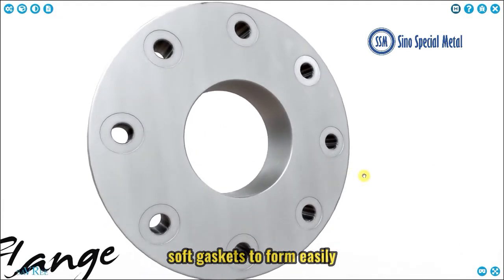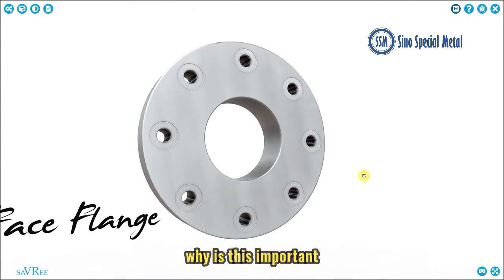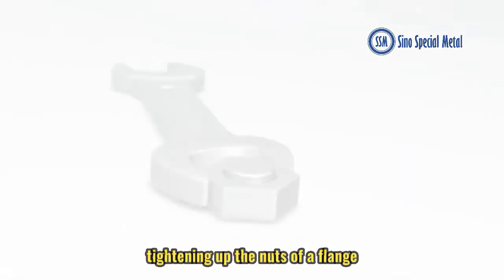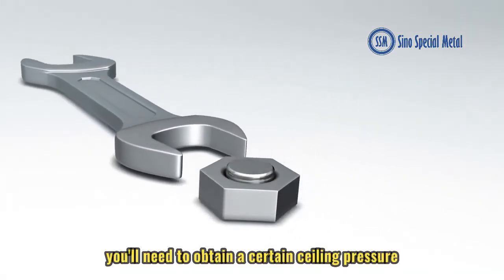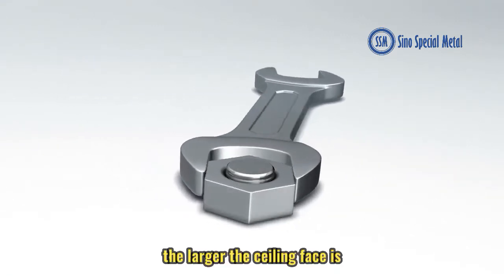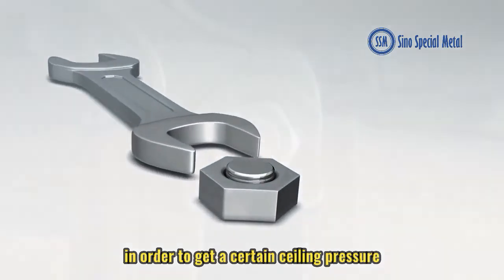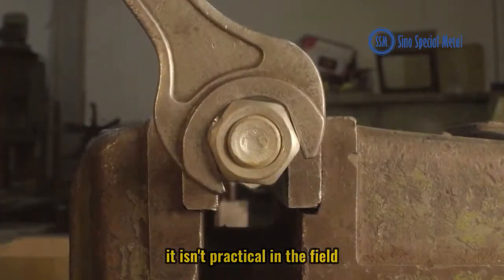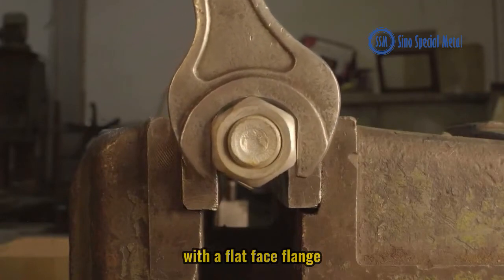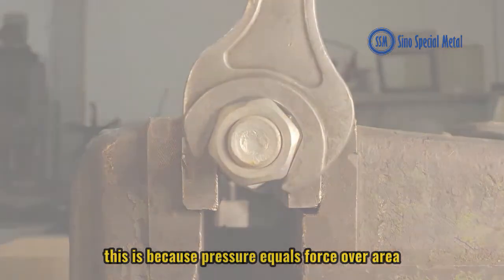Soft gaskets deform easily when applying small amounts of force. Why is this important? Because when you're in the field and you're tightening up the nuts of a flange, you'll need to obtain a certain sealing pressure. The larger the sealing face is, the more force you'll have to apply in order to get a certain sealing pressure. It isn't practical in the field to try and obtain a large sealing pressure with a flat face flange. This is because pressure equals force over area.